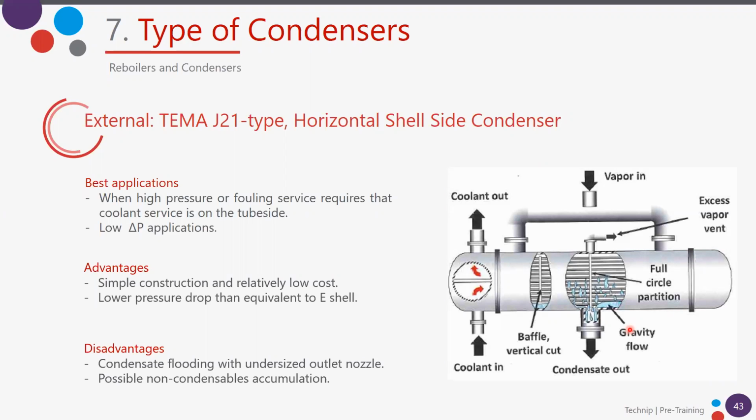You're welcome. And the same for the non-condensables accumulation. It means the vent nozzle shall be designed to facilitate the evacuation of the non-condensables.